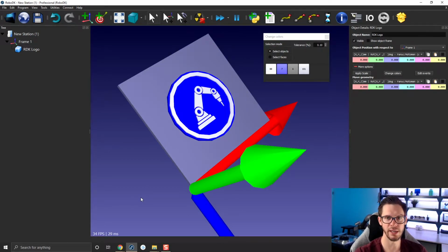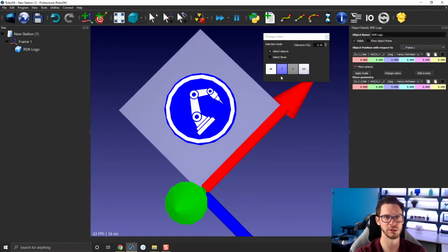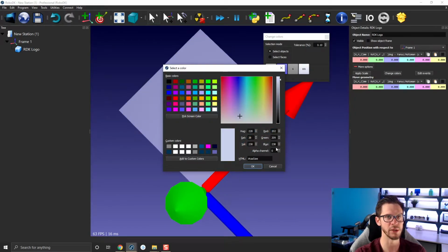The reason why I don't want to right click delete right away is because right click delete is a one-way train. There is no way back from that one. And sometimes some parts of the model you're trying to follow will be the same color as, let's say, the outside layer. So in this situation, you're kind of stuck and you can't really delete all the colors. So before right-clicking and delete, I always hide them, look if I lost any pieces, because here I could always go back and re-increase the alpha channel.